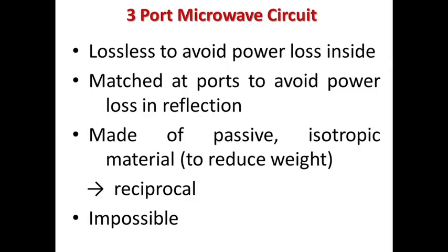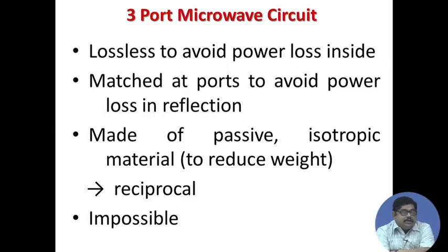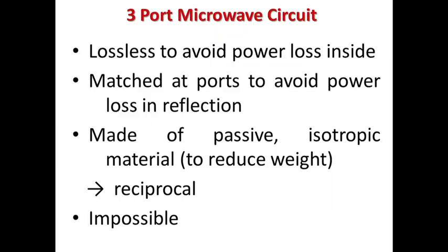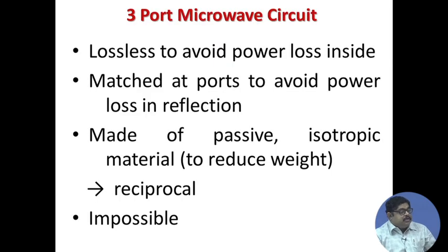it is always desired to have a lossless power divider or power combiner. So, we want the microwave circuit to be lossless, so that no power is lost inside the device. Similarly, we also want that the impedance at the ports should be matched. We have discussed in detail the need of impedance matching, otherwise power is lost in the mismatch. So, we want that at all the ports the device should be matched to avoid power loss in reflection.